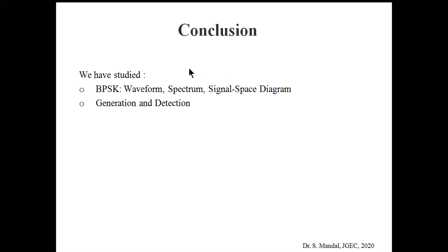So coming to the conclusion, in this class we have studied the waveform, spectrum, and signal space diagram of the BPSK. From the signal space diagram and the spectrum of the BPSK, we can conclude that BPSK is the most efficient digital modulation technique over ASK and FSK, as the bandwidth and the error probability are least for the BPSK technique. And after that we have also studied the generation and detection of BPSK.